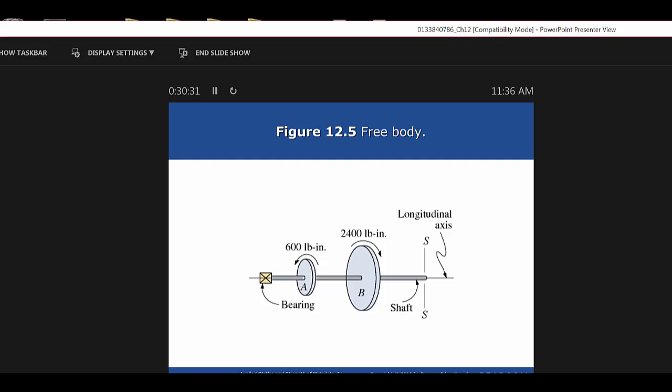What you would do is you would have different diameters on that shaft, wouldn't you? It wouldn't all have to be the same diameter. Now, if you wanted to over-engineer it, I guess it would be. Or maybe the pulleys aren't set up like that that you're trying to buy. They'll have different diameters, so you have to make sure that the internal diameter on a pulley that you wanted to slide onto a shaft would still allow you to create a shaft big enough for that.